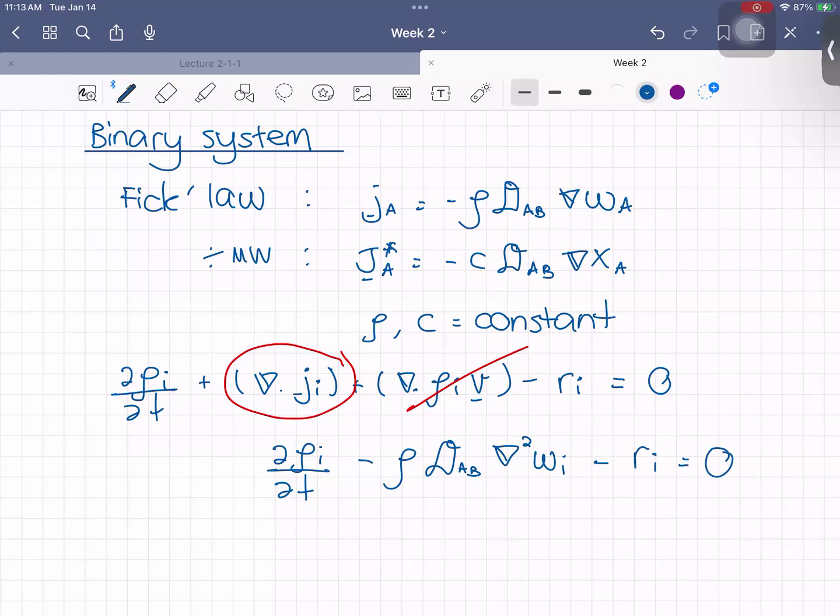So now you can apply this equation and plug all the terms into the equation and solve it. Because if you use this equation, how are you going to plug the actual numbers into this term? You have to apply Fick's law. In Fick's law here, you can apply the mass fraction, of course, it's the known value, also the constant diffusion coefficient and also the total density. Okay, so now you can solve this equation.